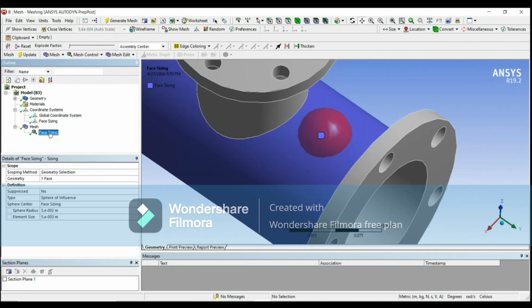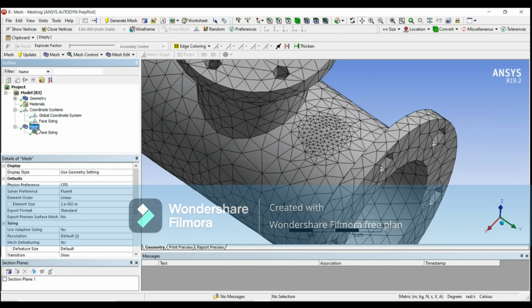This is called sphere of influence, and it comes under local sizing. It is used where you want to make a particular region in the body fine. Sphere of influence can be used with edge sizing, vertex sizing, and face sizing. For a body, we can use the body of influence.